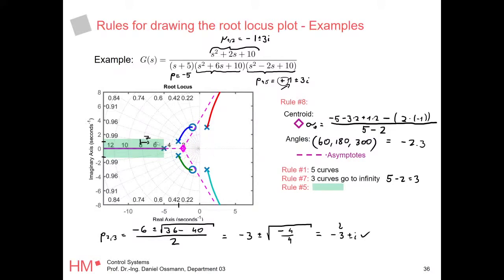Okay, we know that 2 poles need to go to the zeros. Obviously, these ones go there, and these are closer to infinity, so these go along the asymptotes. I mean, if you had drawn this like this, you would have been in trouble to say how this goes.